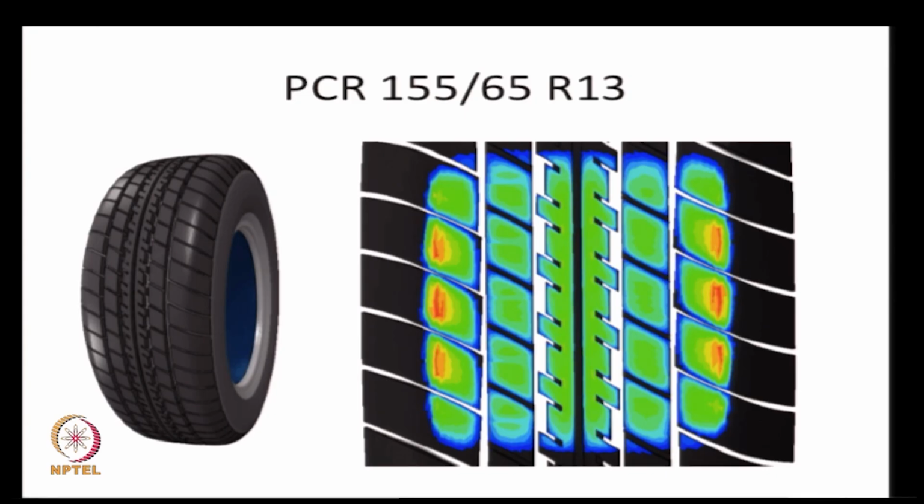Now, that's a typical passenger car tire. You can see the treads there, very clearly seen. There are various ways in which treads are designed. You can see that there are grooves in the tread. These grooves, on this passenger car tire, are there in order to carry water or minute sand as you go over, say, a sheet of water. In other words, they are channels for the water to escape as you go under wet conditions, right?